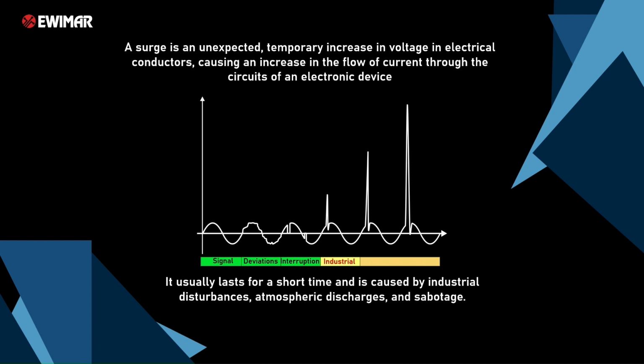Interference in the form of overvoltage may result from the operation of connected devices or associated equipment, but manufacturers of individual components and developers of complete installations usually anticipate the elimination of such adverse phenomena at the design stage. Another and more dangerous source of surges is atmospheric discharges, which affect electrical and electronic installations in many different ways. Sabotage, caused by the deliberate use of high-voltage generators or power lines, is also a possible source of surges. Individual sources of overvoltage, the hazards they pose, and ways to counteract them will be discussed in the following sections.